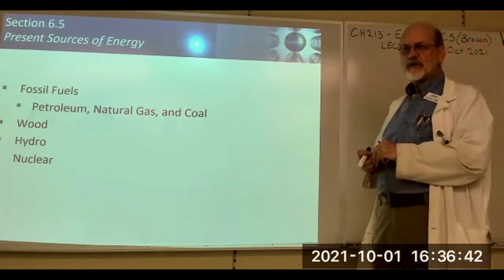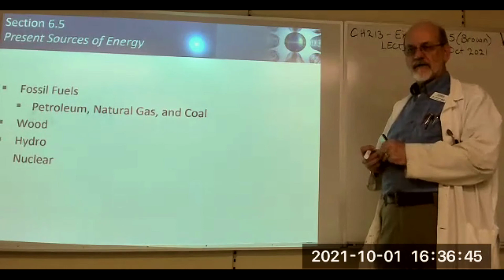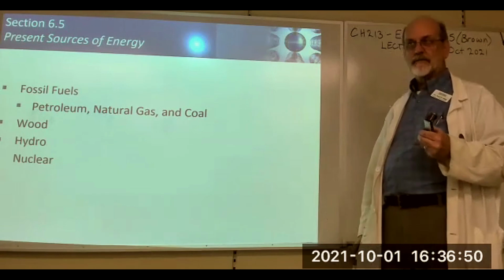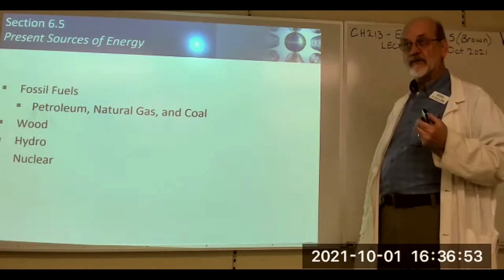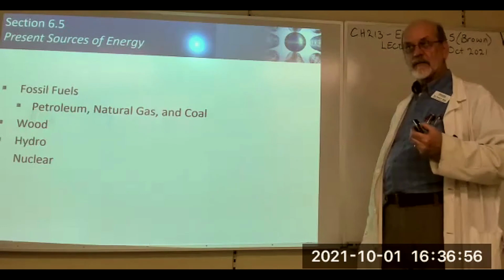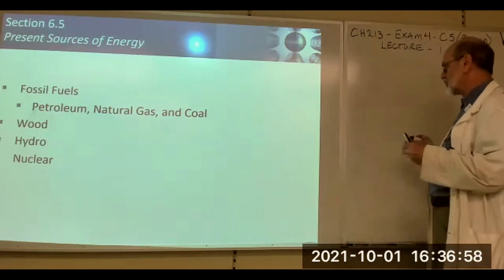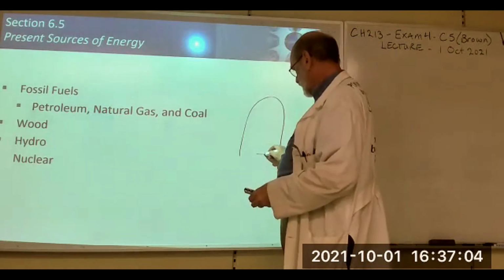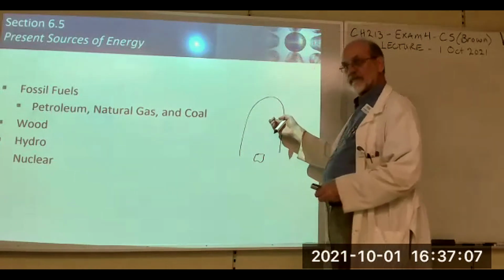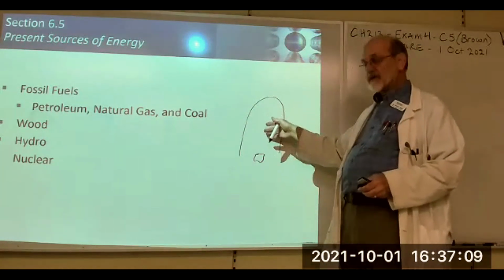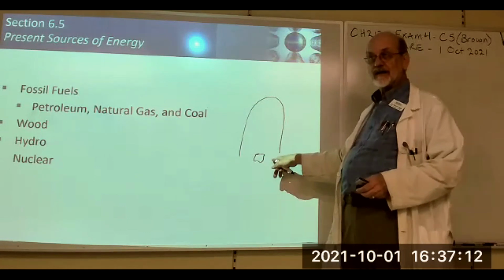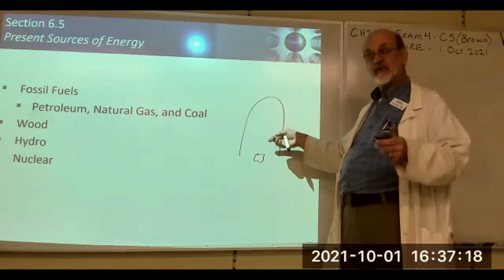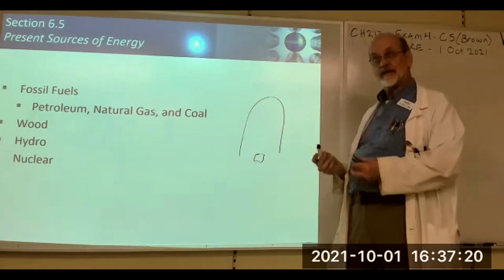The problem in this country with nuclear power is that somebody made the decision along the way to use pressurized water as the transfer medium for the heat. That is a mistake. That's why all the nuclear plants have these huge domes, and the reactor is this little bitty thing down here. The reason for that dome is that if this pressurized water springs a leak, it instantly flashes to steam, which is 1,000 times as much volume as the water. You need a big dome to contain it.